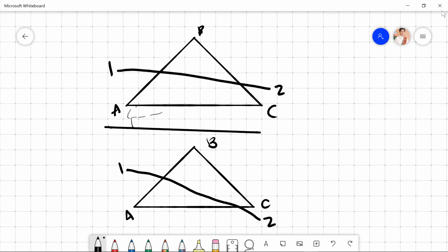So, let's make an imaginary cutting plane that is an edge view in the top view. Okay? So, if it is an edge view in the top view, it will intersect AB at point X here. Right? And it will intersect BC here. So, X is along AB. Let's say, when we project X, just as an example, it goes here.